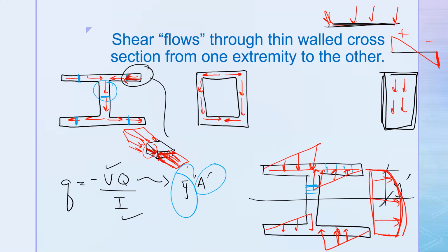In fact, it's going to start such that this stress in the web is equivalent to the stresses or the shear flow coming from the flanges. So this should, I believe, be double what these are. So then they'll add together as they go up.